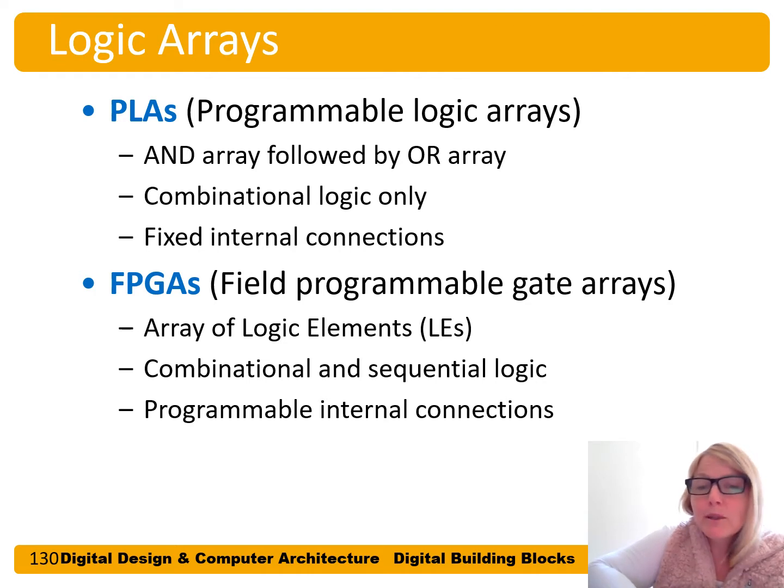Both are still used because PLAs are cheaper in general than FPGAs, because they're simpler and they only do combinational logic. But FPGAs are common for systems where we need both combinational and sequential logic.